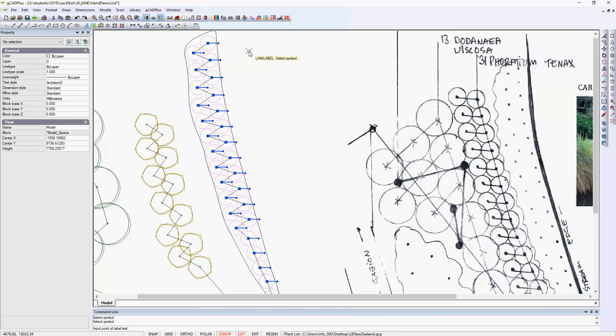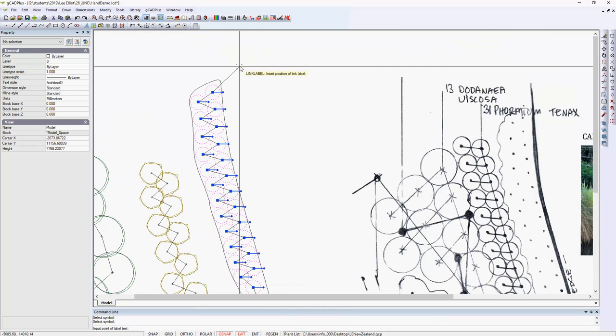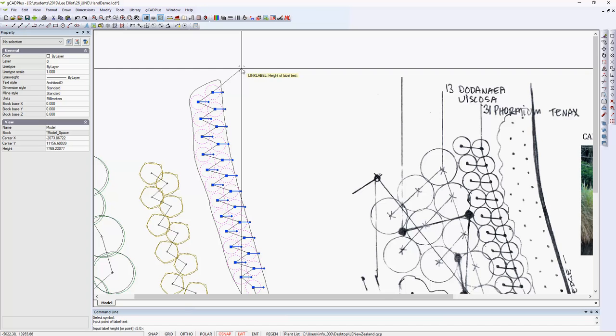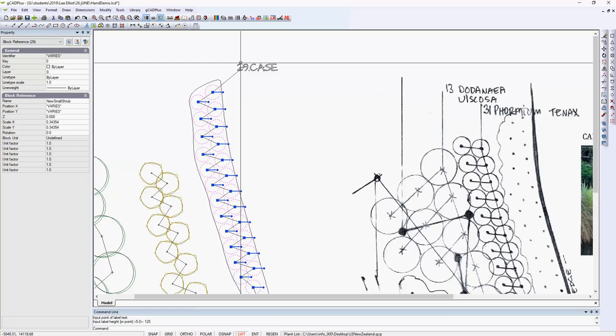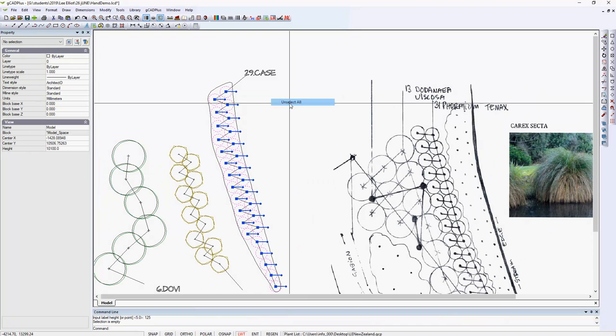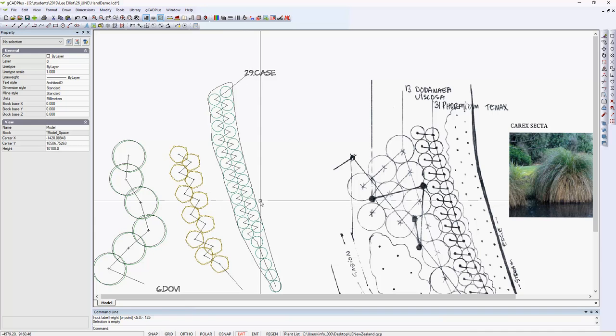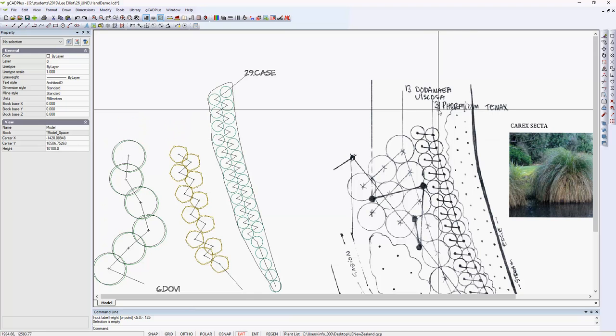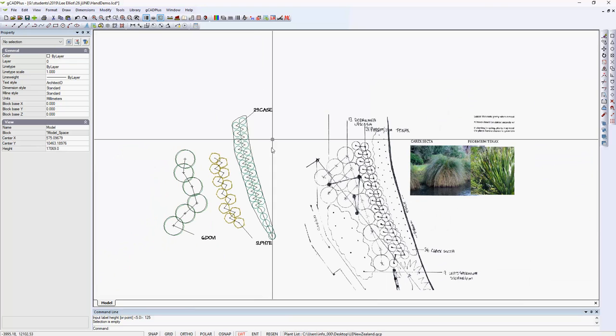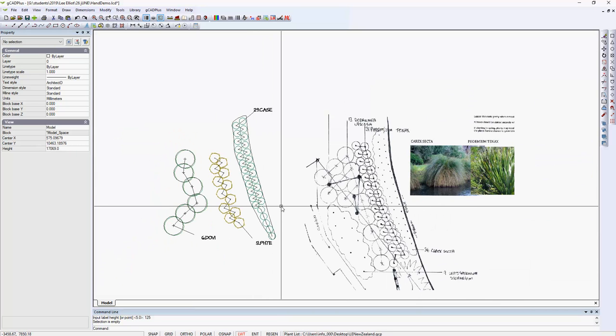They're all in. So for the input of the label text, maybe we want it up here, and for the height, we can just indicate the height that we want, or type a value. I'll just type 125 and enter that in. Let me unselect all. The tool has counted all of the symbols that are in that zone and given us a number. With hand drafting, you have to mark them all with a highlighter and then count them. In this case, we do it on the computer.